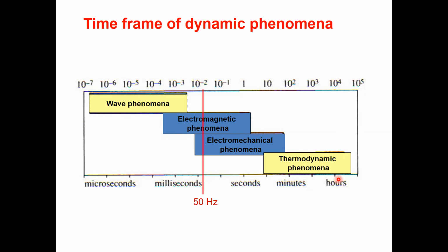So what you will do, you will first start your combustion process in the furnace, then you will have a certain amount of heat being developed. Let's say you have something like 900 degrees centigrade developed in the furnace, and then you will have your water being converted into steam. And again, it should be at a much higher pressure. So again, you will have a superheater in the boiler. So that process again takes time.